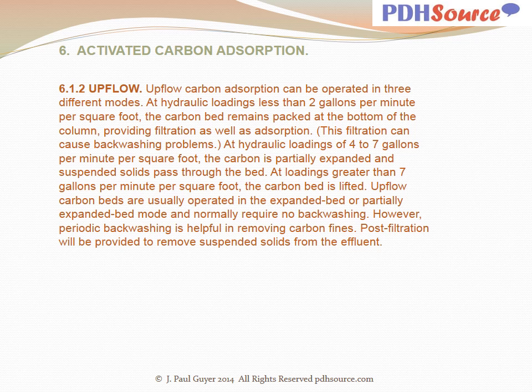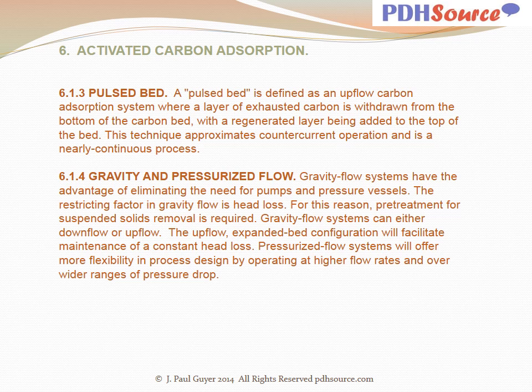Upflow carbon beds are usually operated in the expanded bed or partially expanded bed mode and normally require no backwashing. However, periodic backwashing is helpful in removing carbon fines. Post-filtration will be provided to remove suspended solids from the effluent. A pulsed bed is defined as an upflow carbon adsorption system where a layer of exhausted carbon is withdrawn from the bottom of the carbon bed, with a regenerated layer being added to the top of the bed. This technique approximates countercurrent operation and is a nearly continuous process.